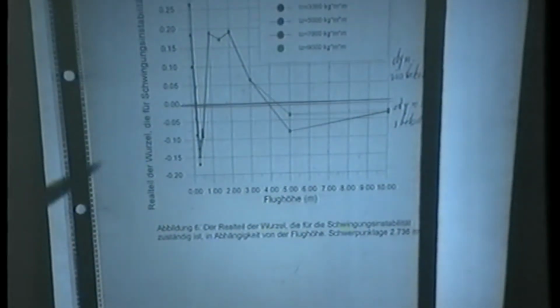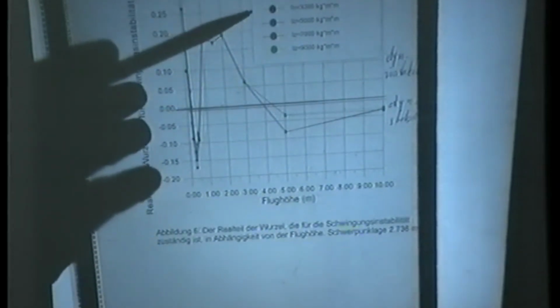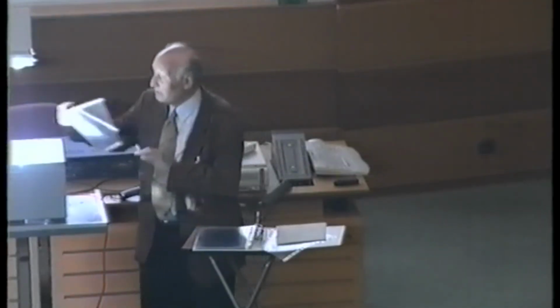So this is very helpful for aerodynamics, and from that we then tried to find out, is that identical with the theoretical results. This is dynamically unstable, and here it's stable. And here you see results with different moment of inertia. So it is important that you have not the model rules only with point of weight, but also moment of inertia. You see how important the moment of inertia is to remain in the model rules. From that we can then correct the predictions.